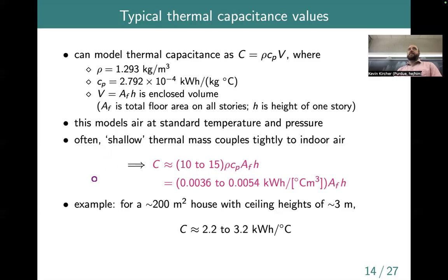Another reason for this is that the temperature of the air in this room is not a single number. It's really a three-dimensional scalar field. So depending on the X, Y, and Z coordinate that you choose in the room, you would have a different temperature measurement. In particular, due to thermal buoyancy, it'd be hot near the ceiling and cold near the floor, probably. So when we put in heat from radiators or from an air conditioner, there are mixing effects, and it takes some time for the air to mix, and then for the temperature change to actually show up at the wall thermostat. So there are delays associated with that physical mixing process, and those are another reason why a slower model, basically a model with more thermal mass in it, tends to fit the data better.